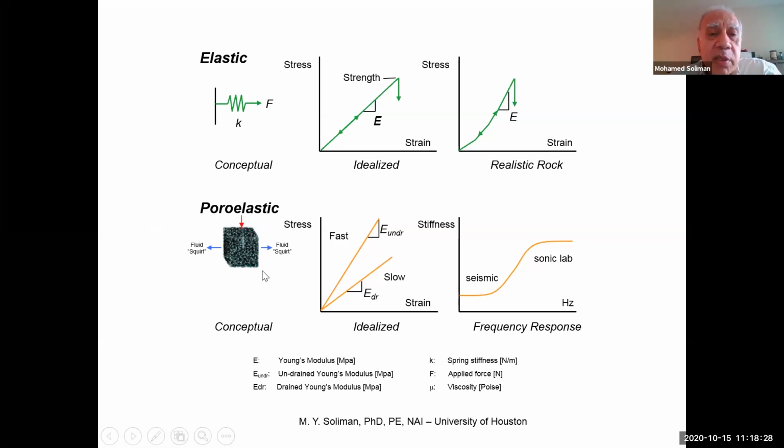Poroelasticity is a very important concept to understand, where it affects the fracture and affects the rock behavior, and we'll talk more about it in a few minutes. For example, here we have two straight lines showing whether it is drained, same as the one above, stress versus strain. I probably should have defined what stress is. Stress has the units of pressure, psi, force per unit area. However, it is not the same as pressure.